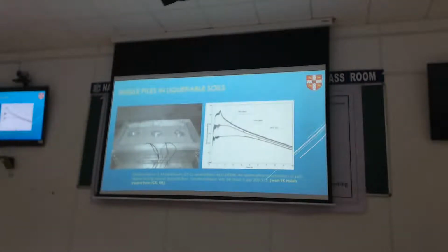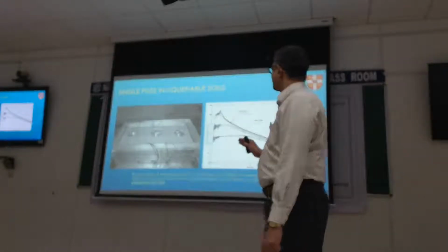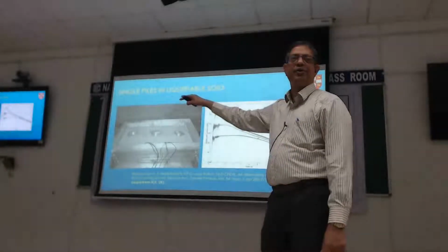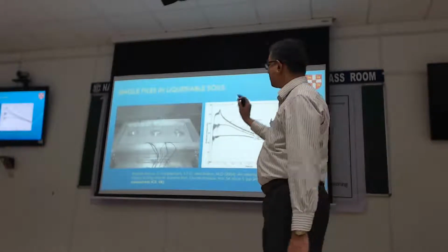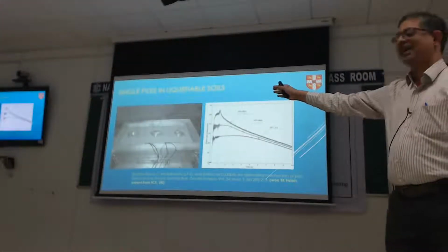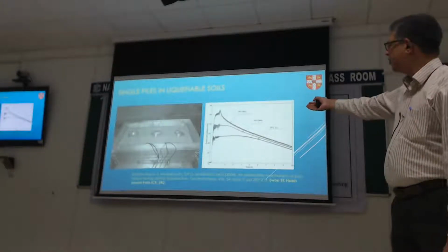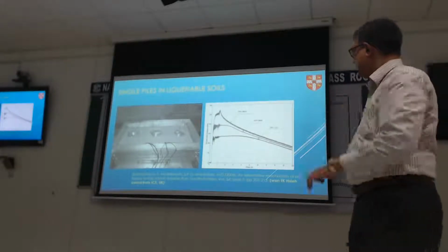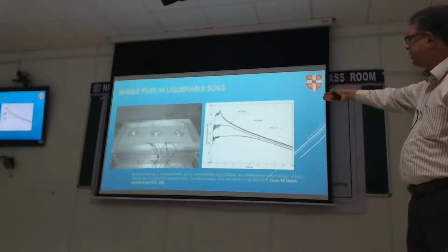And here is a picture taken immediately after the test, where you can see the sand boils. I told you sand boils are a clear indication of liquefaction. So that was good. But we don't rely on just the sand boils. We measure the pore pressures at different depths, so we can see how the pore pressure is built up in the soil. So clearly, as we should, the pore pressure builds up.